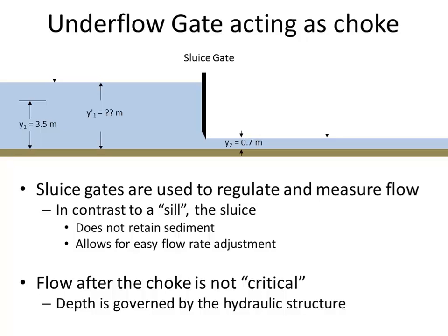So what happens in a scenario where there is enough energy upstream to make that happen? Let's say there's more than enough. Does the water level come up past the gate bottom? We said the upstream was 3.837. Let's say on the downstream it was 3.5. So there was enough without it pooling. Okay, then it won't pool. But would the water level past the gate rise, or would there just be extra energy? The water level would be unchanged.